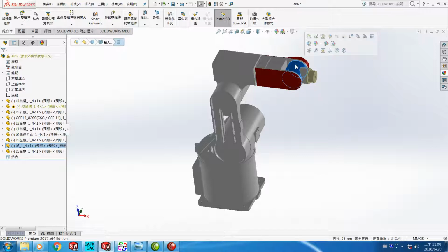This one, AJ6, with the model: these two components we leave on the screen and remove the rest of the components, and change the color of them into yellow and save another file name as AJ5.prt and then save another file name as AJ5.iges. The last one is this one.